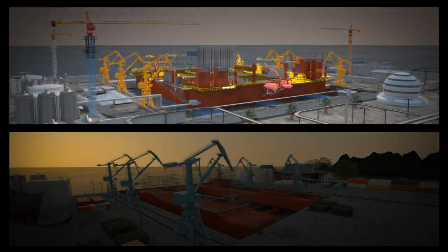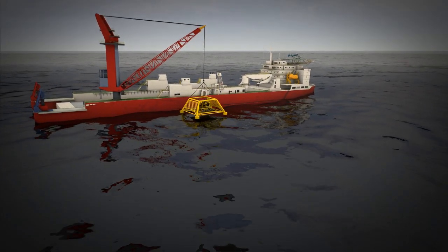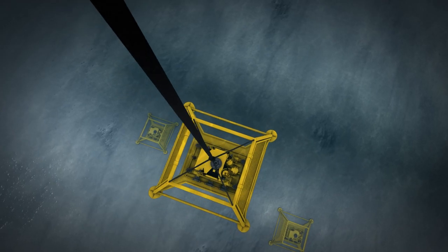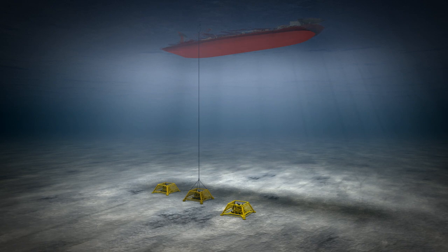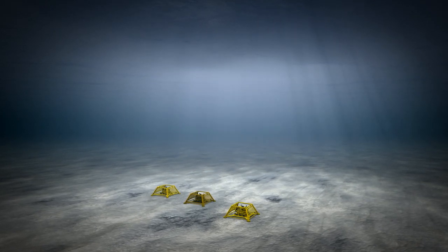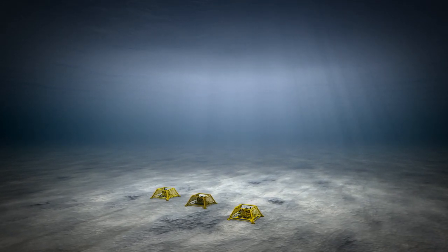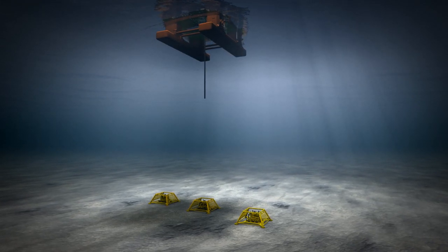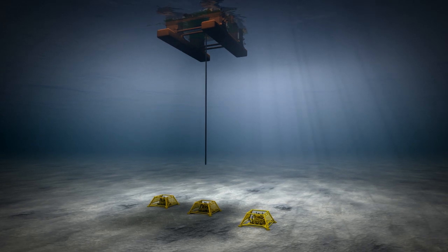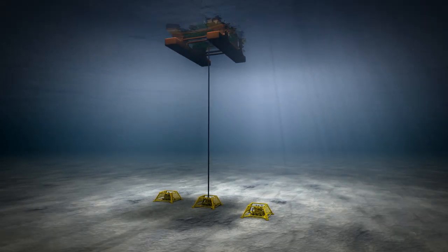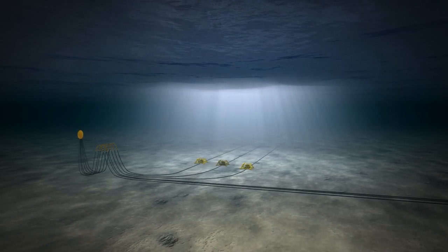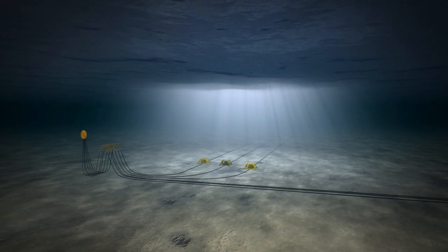While the hull and topside are being built, preparations are underway at the location in the North Sea. The subsea templates that have already been prepared in Scotland need to be put in place on the seabed above the reservoir. When this is done, a drilling rig, like the one used to drill the exploration well, arrives at the scene. This drilling rig is then used to drill and complete all necessary production wells through the subsea template. Installation of necessary riser and other equipment is then carried out and left at the scene, awaiting the new production unit's arrival.